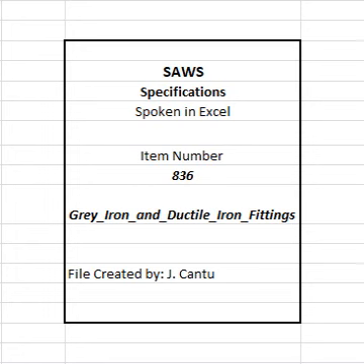836.5 Construction. All fittings shall be either restrained mechanical joint compact or flange joint, unless otherwise specified in the contract documents. All mechanical joint compact fittings shall be installed using approved restraining glands in accordance with SAWS material specification. Item No. 113-02, Ductile iron restrained joint fittings for use on ductile iron. 1. No separate payment will be made for these restraining glands.